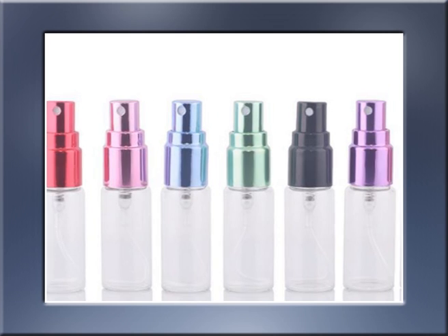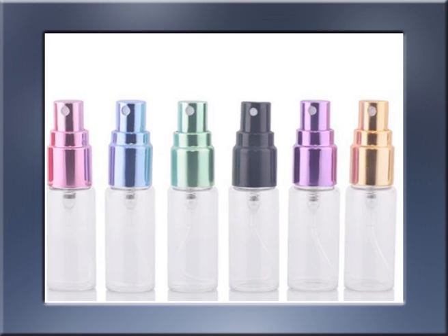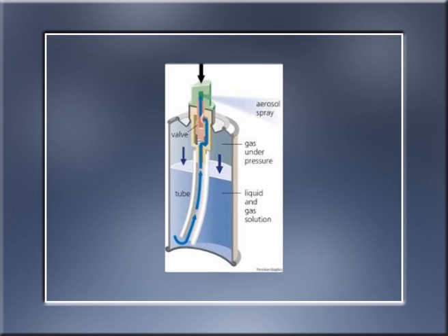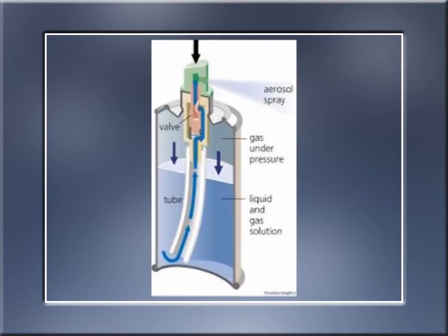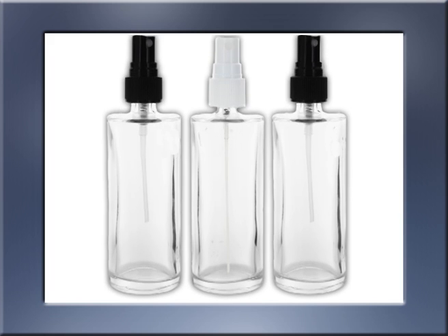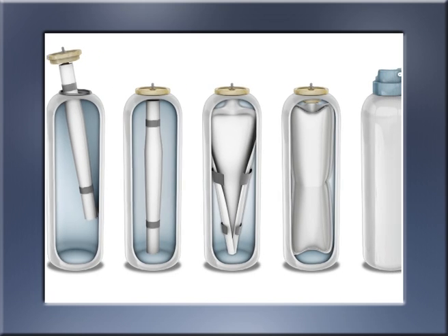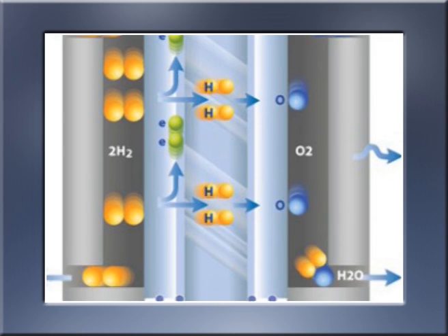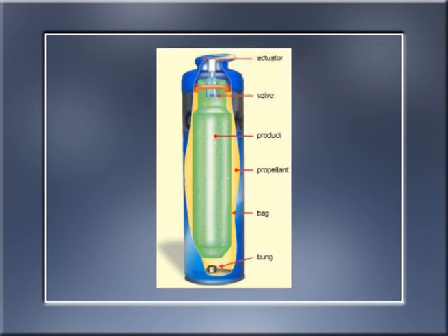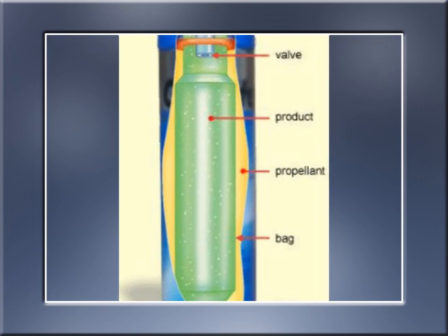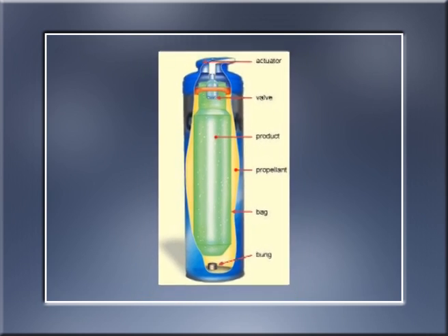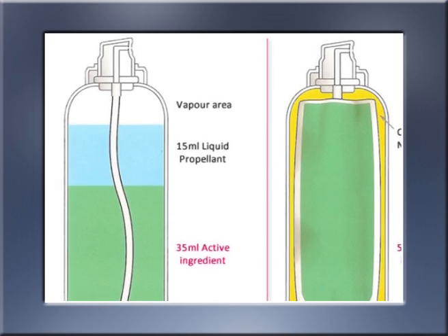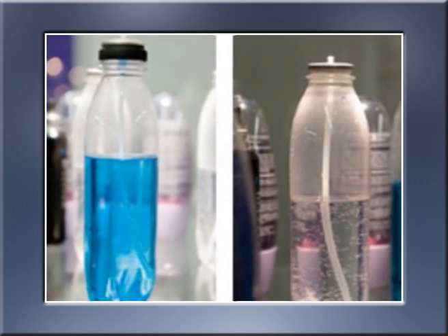Therefore, glass containers are used in products that have lower pressures and lower percentages of propellants. When the pressure is below 25 psig and less than 50% propellant is used, coated glass containers are considered safe. Plastic containers have had limited success because of their inherent permeability problems to the vapor phase inside the container. Also, some drug-plastic interactions have limited the efficacy of the product. To increase the resistance to breakage, plastic coatings are commonly applied to the outer surface of glass containers.